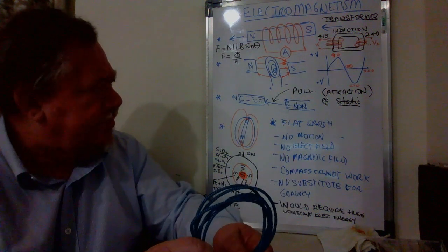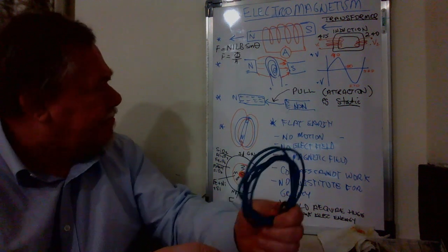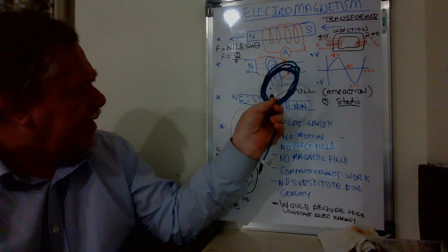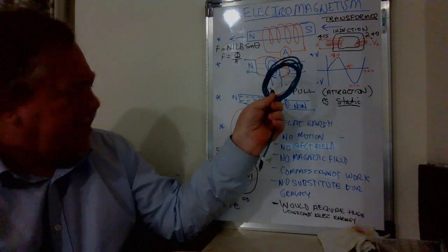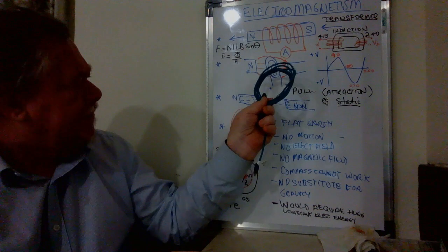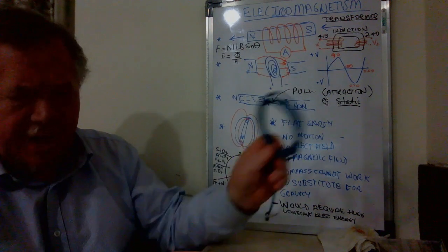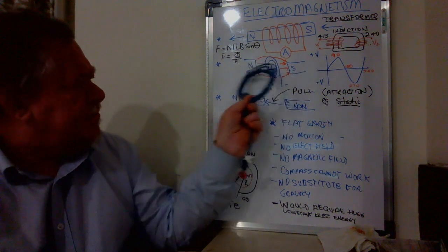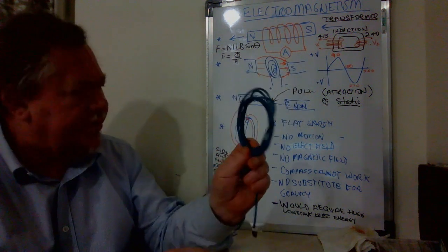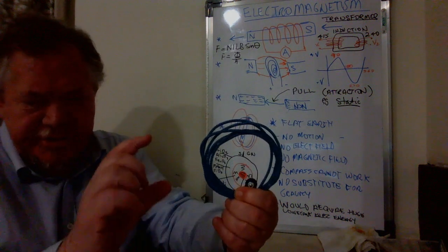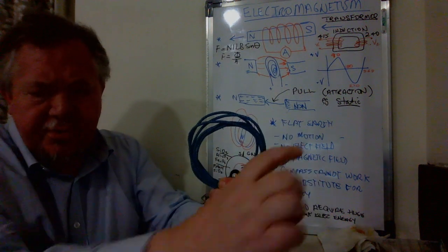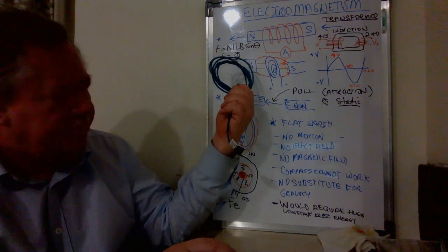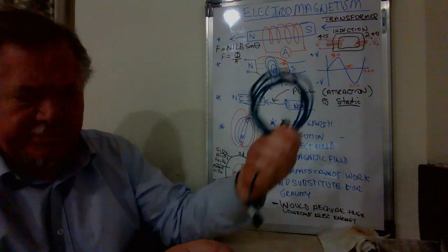That's magnetic induction. Now, over here, I've got, if you like, the makings of a generator. So last time I spoke to you about how a generator works. We've got a magnet either side of a coil. So there's a coil. Either side of this coil, we have a magnet. So we'll have the magnet, north will be facing one side of it, south will be facing the other side.